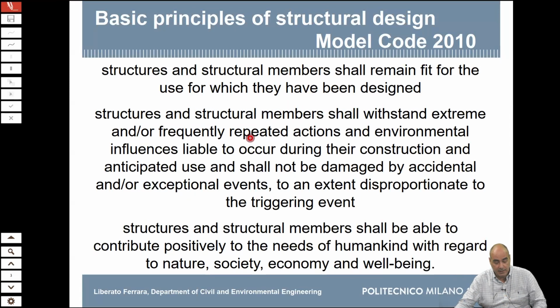But besides that, we also have to take into account, and this we will see tomorrow, this has become even more important. The structure shall withstand extreme events, an earthquake, an explosion, some kind of events that you can imagine, but you know, it's a very long return period. This is the way in which we statistically handle that.